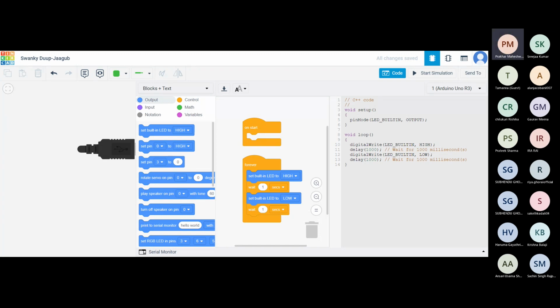So what happens is when we start our code, if there is nothing above void setup, outside these two functions, then our code just jumps into the function called void setup. So we define our pins, and we initialize certain things or anything that we want to run just once. We put all those things in void setup.